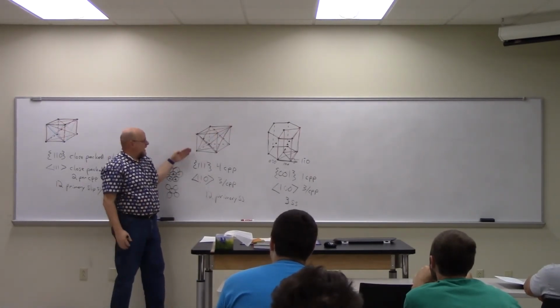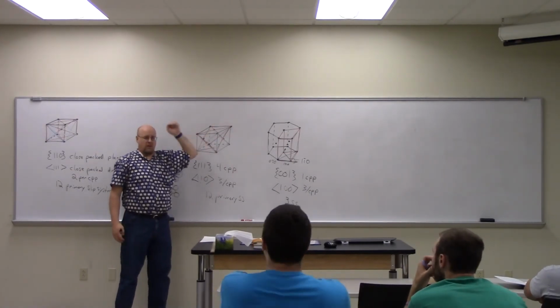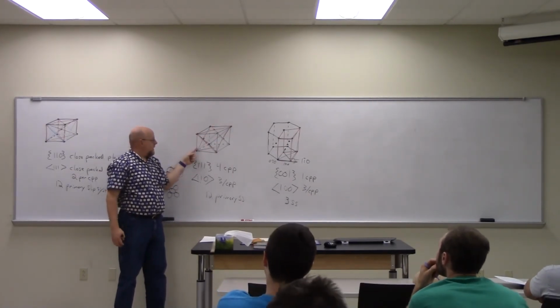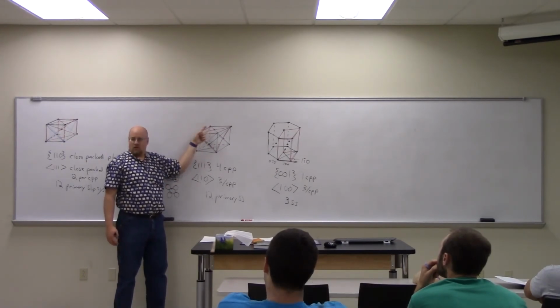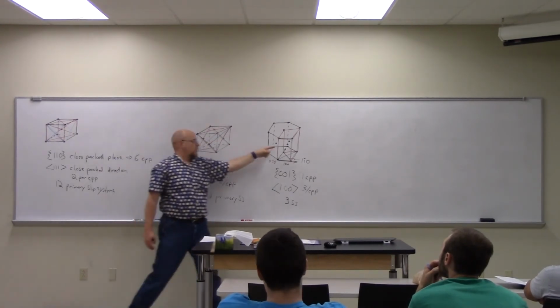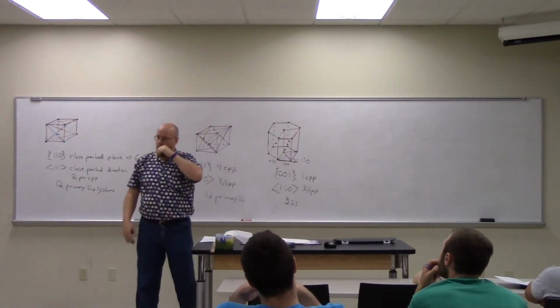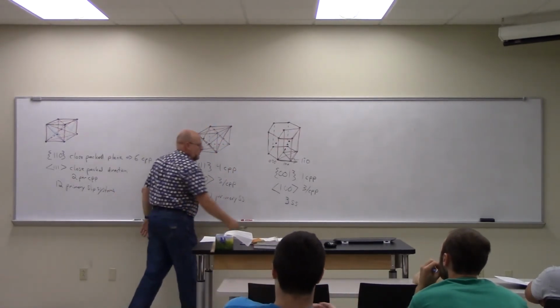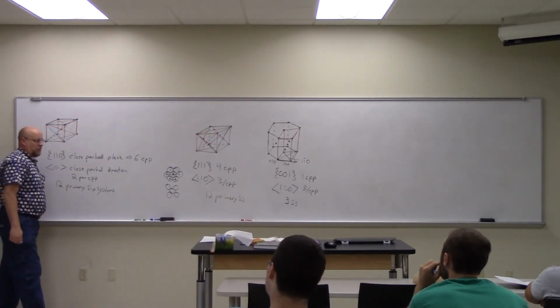And so we can actually get a direction of propagation across those planes. Right? So we have that back face, we have an A, B, C configuration where the atoms line up and make another close packed plane in another close packed direction. Here, we can't do that because we have the A, B, A, B, A, B structure. So the hexagonal system only has 3 slip systems. The face centered cubic and body centered cubic both have 12.